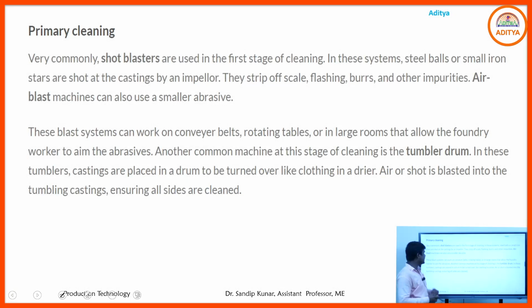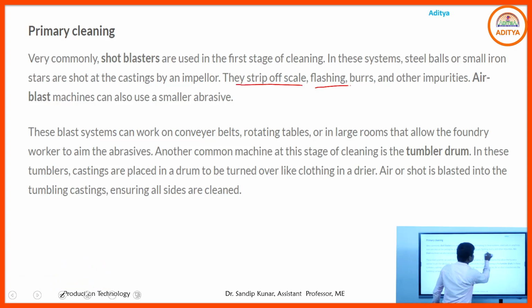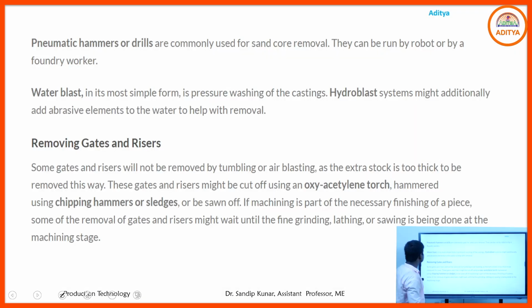Okay, primary cleaning. In primary cleaning, we strip off scale, flash, burrs and other impurities using air blast machines. Sometimes pneumatic hammers and drills are commonly used for sand core removal.